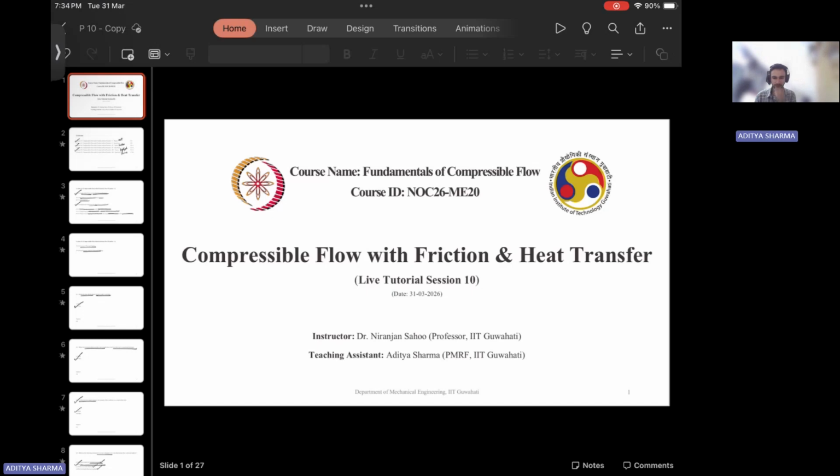So here it says that heat addition is the driving force for change in entropy. Okay. Then there were flow properties, how we can calculate flow properties in case we have heat addition in compressible flows. So expressions are there. So you can go through lecture number 23. Link will be in the description. Then concept of thermal choking. So because of heat, you can attain M equals 1.